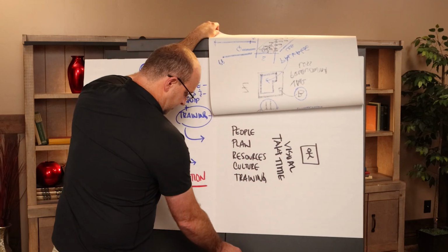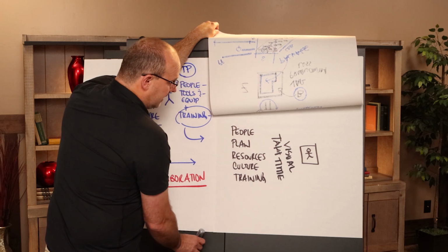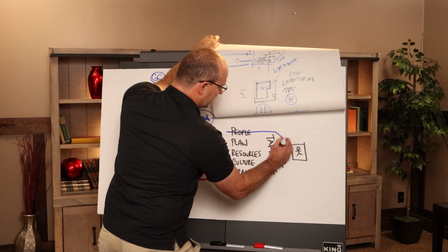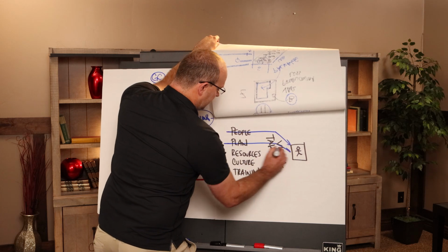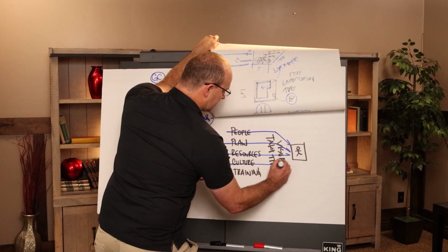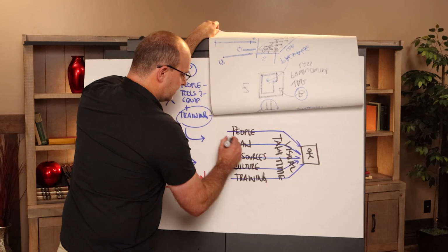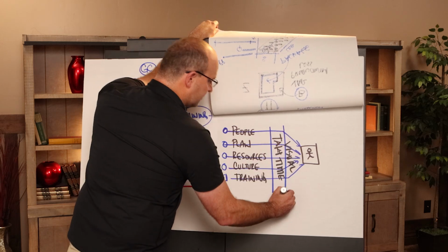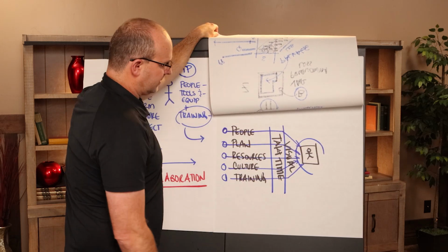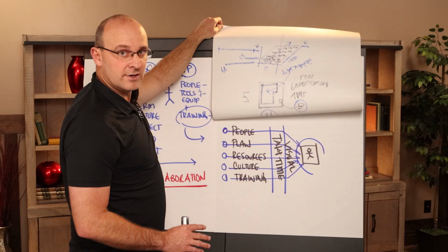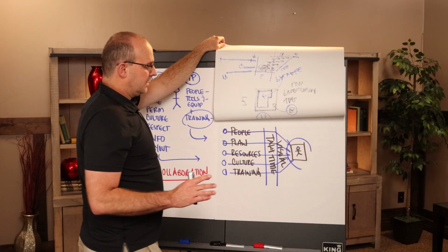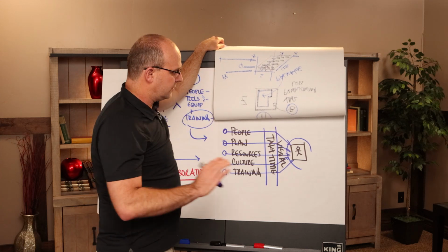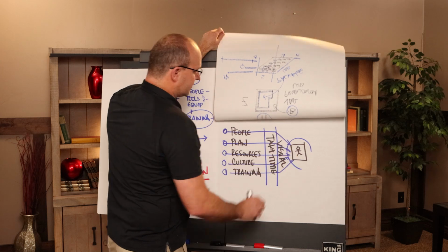And what you'll see here is a really interesting pattern that I like. It's not that we have these separate disconnected things, it's that everything we do is to get that crew what they need to go build that work inside that work package, and it's a brilliant concept. So these things have to run through the takt time in a visual manner to enable the trade partners to have what they need. So that's the pattern. That's how I encourage people to look at it. Nicholas Modig in his trainings always talks about organizations thinking of themselves as silos. No, no, no. Everything should create flow over to that work package.